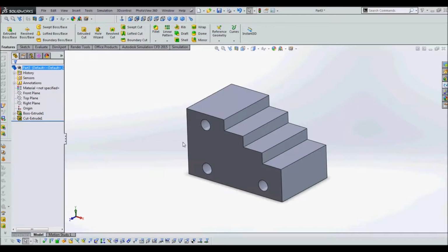And one thing we're going to do now is you'll note that each of the sketches we've been making has been turning invisible after we've done our 3D operation. One of the things that we can do is we can go in and, for instance, I'll open up Cut Extrude. I will click on the sketch here with the left mouse button a single time, and we have a couple options we can use. So we can either roll back, which will move this bar back, and this bar essentially determines at what state the model is in. So if you were to develop a full model with many features, you could drag this bar back and it would bring it back to whatever state it was at that point in time.